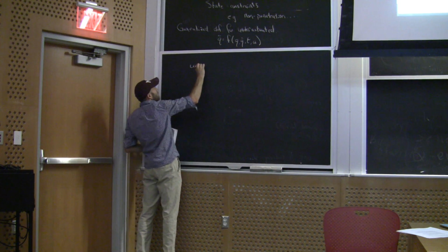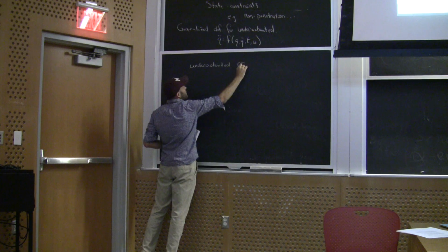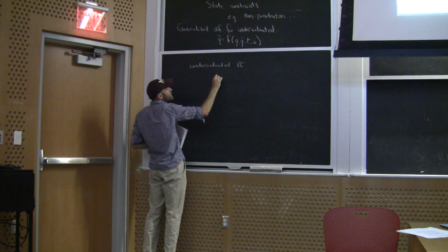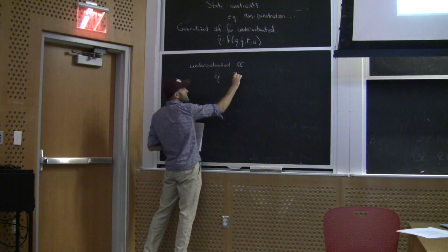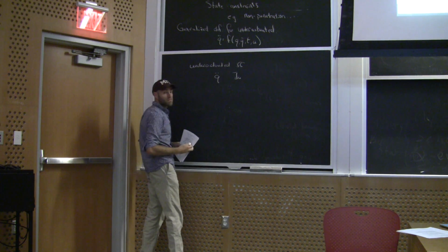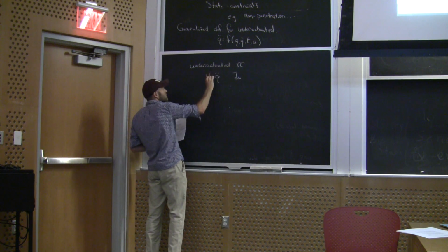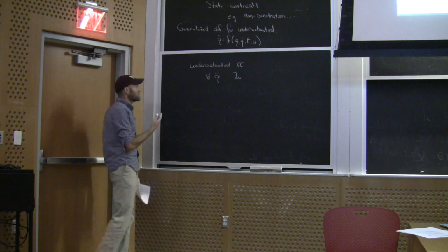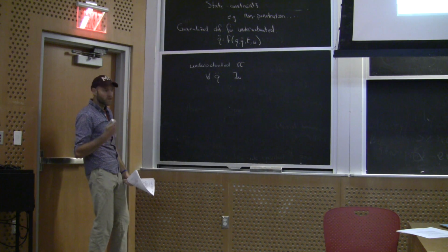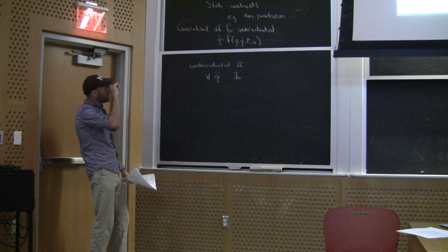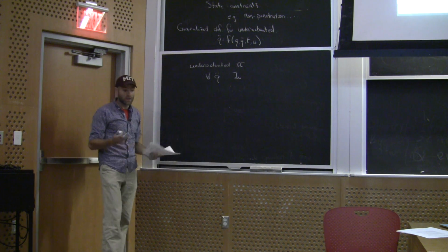It's underactuated if basically I want, for every q double dot, I need that there exists a u which generates that q double dot, right? I'd like to be able to produce arbitrary accelerations, right? I'd like that map to be well defined so that for every q double dot, I could pick a u. If I want to accelerate in some direction, I can do that. I can find the u, right? And input constraints will break that, and other constraints will break that.